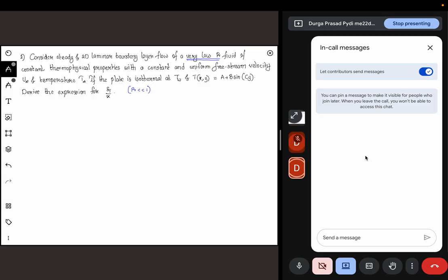How is it different from the one that we derived, like say half an hour before? We have solved the energy equation. Yeah, there are two key differences. The first one is we said explicitly that it has a very low Prandtl number, whereas in the previous derivation we have used that delta T is less than delta, which means Prandtl number is greater than 1.